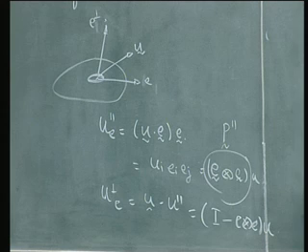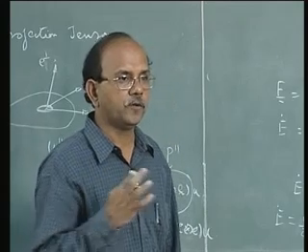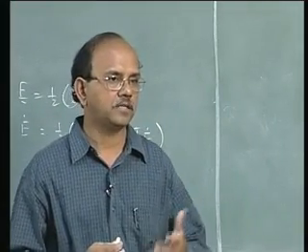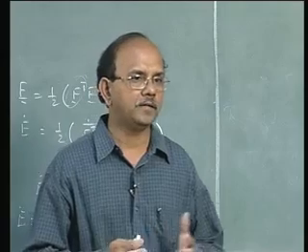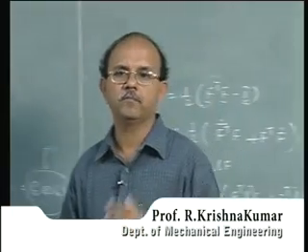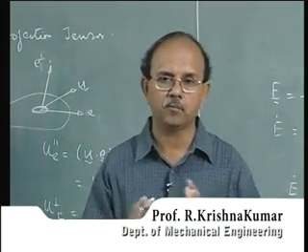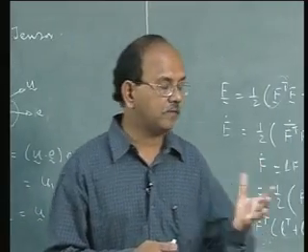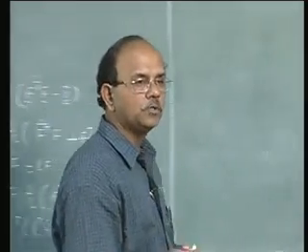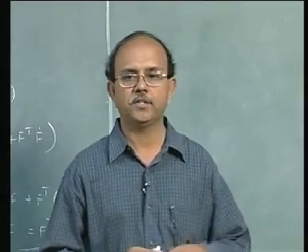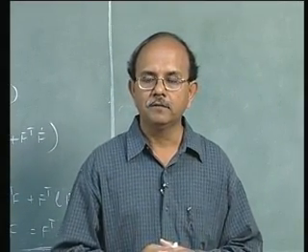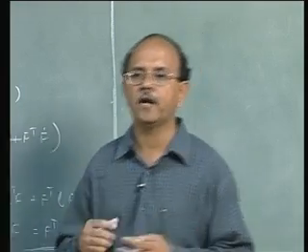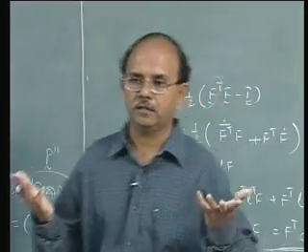Or is it that W dot is equal to R dot? So if you remember, we had seen yesterday, or maybe the last class or before that, we had looked at F very closely. The last class we said that we can split this polar decomposition, and we have F split up into R and U, and we said that R is a rotation and U is a stretch and so on. Now, that is one rotation. So rate of rotation, if I ask, you may say that it's R dot.